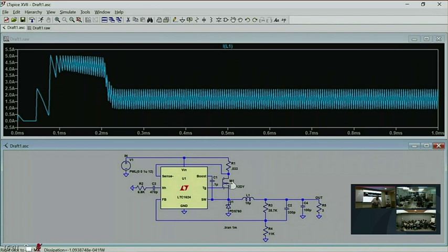Now, voltage mode is the older method. It was used in the 1970s. And to understand current mode control, or to understand voltage mode control, a voltage mode controller is basically a glorified comparator. So here's our comparator, and that's basically our controller. That is what controls the switch. Let me instance this up with a buck controller.